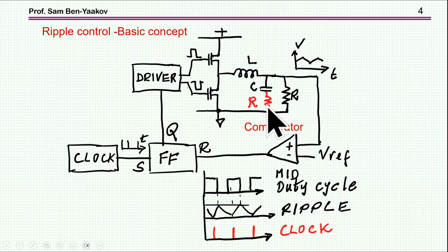And here is the basic operation. What we see here is the output voltage. It's the ripple, very typical. You see that the peaks are about 5 volts, and this is because after division we have this sense voltage, which is compared to 1 volt.